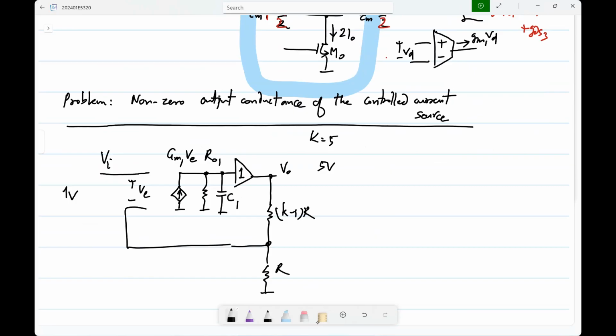So basically, of course, you can evaluate the transfer function and all that. We'll do it. But what do you expect now? With a DC input, the output steady state should be DC, right? And of course, this voltage here is exactly the same as the output, right? Because it's just a buffer. So now, if you have any non-zero voltage here, some current will be flowing through the resistor. Where will that current come from? From the capacitor. Okay, if the current is flowing through the capacitor, it's not steady state, right? What is it, if you have DC steady state, what does it mean?